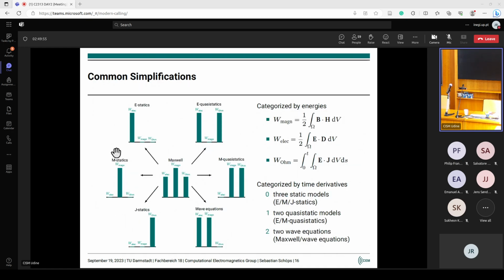But on this slide, there are 3 effects included. There is the magnetic world, the inductive things, there's the electric world, the capacitive effects, and there's the ohmic, the loss part. For magnetic machines, you either just look at magnetics, or magnetics and the losses, because of course you need the losses to compute the energy efficiency. That gives us a subset of these equations, and that's also very similar to Navier-Stokes. In fluid mechanics, you rarely have to solve the full set of equations, to my understanding. In many cases you have special cases where you can luckily make your life easier.